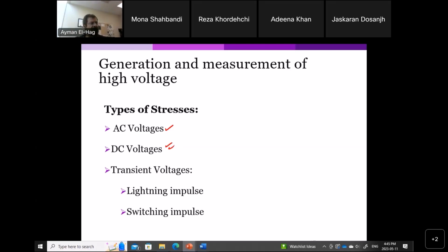This is a hot area in high voltage electrical insulation, because we are used to the AC system, but we are not used to the DC system much. In the DC system, there are different forms of aging and more severe stress on the insulating material. So whether you are putting the material in an AC or DC system, before you install it, you have to test it under AC or DC voltages. So then you have to generate this AC voltage or this DC voltage.